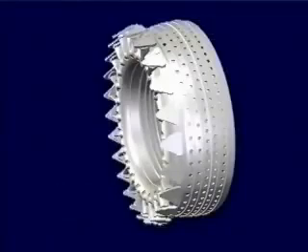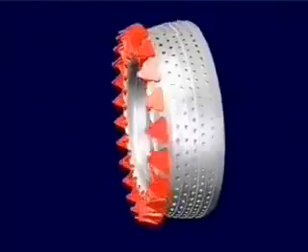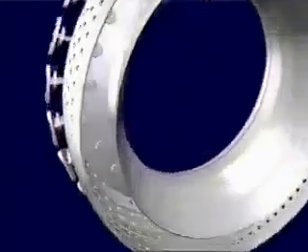This is accomplished by adding fuel through a series of injectors and igniting it, further increasing the temperature of the mixture by 1,600 degrees. The higher the pressure of the air, the more energy will be added during combustion, and the more efficient this process becomes. This is why the compressors were used to increase the air's pressure. Now, the superheated and compressed air mixture is ready for the next phase.